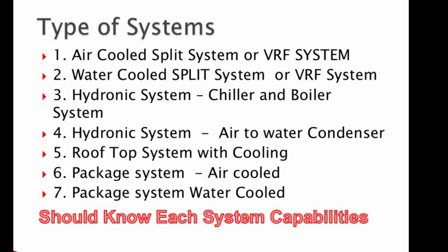1. Air-cooled split systems or VRF systems. The condenser is installed outdoors and cooled by air circulation. 2. Water-cooled condenser systems. Similar to air-cooled systems, but the condenser dissipates heat using a water system.